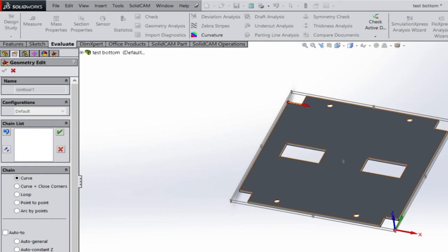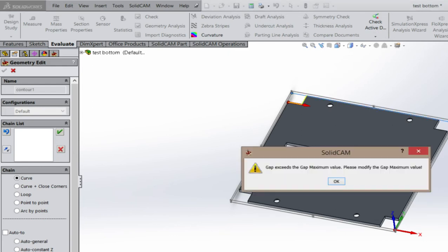I mean, the tool can cut either way. It has to do with the fact that the tool is spinning clockwise. This will climb. Tool is spinning clockwise. Climb, climb, climb. If the tool is spinning clockwise here, I'm scooping, scooping, scooping. So I want to climb here.